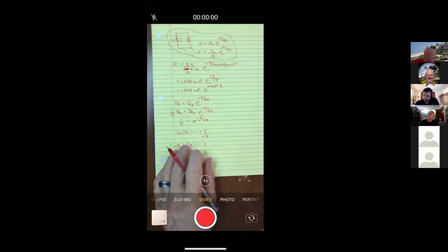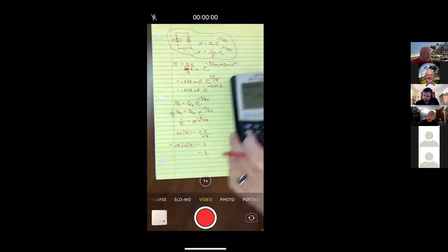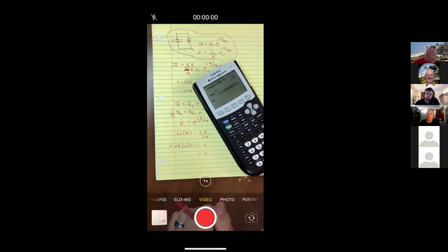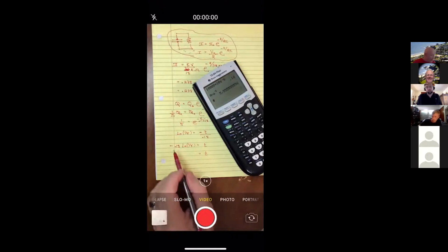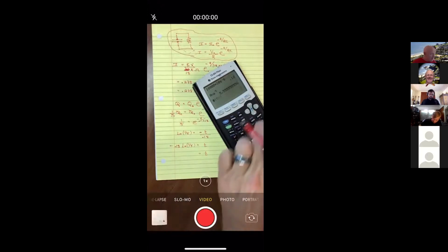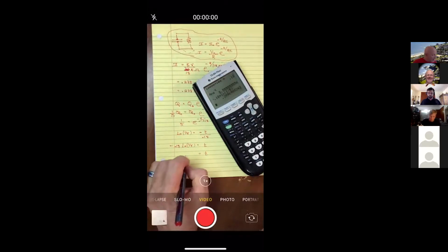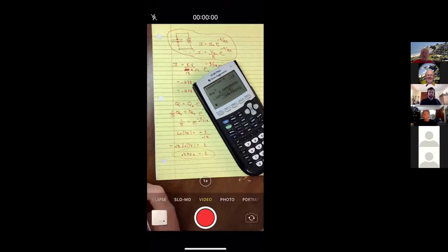And so let's see how long before it has only 1/5 of its charge. And I'm pretty sure we'll be well under a second, but not as low as I originally said. All right, so I'll go negative 0.18 times the natural log of 1 divided by 5 and hit enter. And it looks like a little over 1/4 of a second, almost 1/3 of a second, 0.290 of a second.